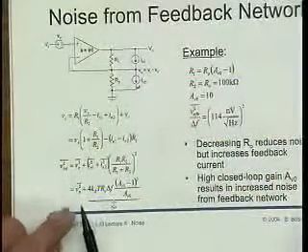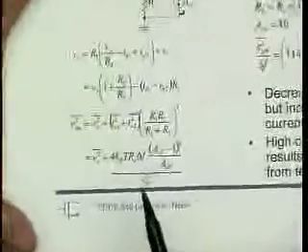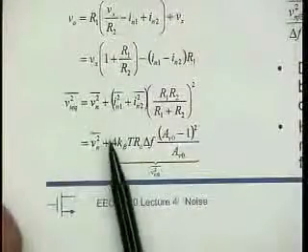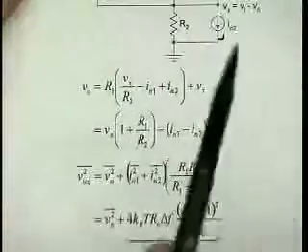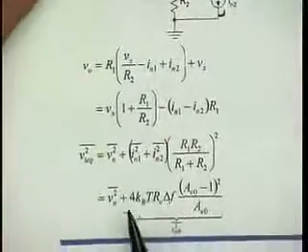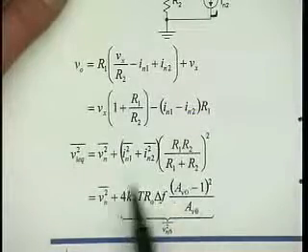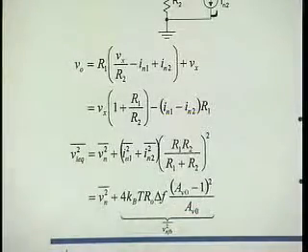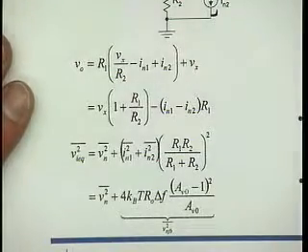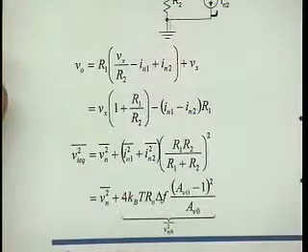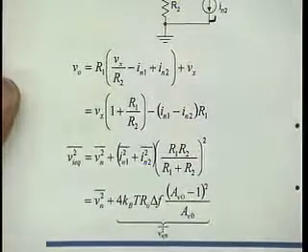Okay? So the input-referred noise, then, if you can use a little bit more zoom, please, is first of all the noise from the amplifier. I mean, it sticks here, obviously, right? That's the amplifier noise, no change there. And then I also get the noise from these resistors, and I simplify this a little bit. You can go through these calculations yourself, not very difficult, but do it just to have yet another example of how to calculate noise. It's easier to do it now than during the midterm.